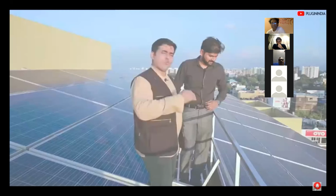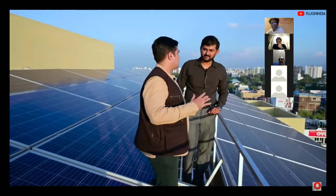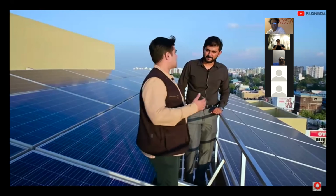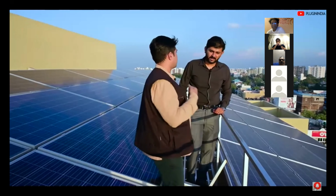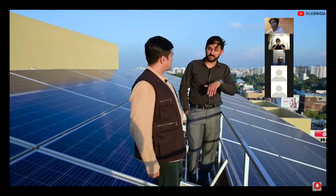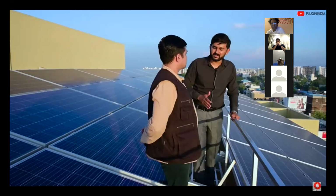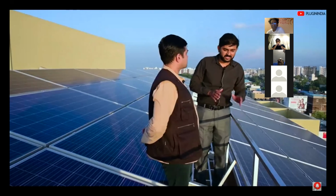Fantastic. 4 months of a year in Pune, you have a pretty cloudy weather. It's the monsoon season. And is there a drop in the production of electricity over here? Yeah, definitely, because the clouds will obviously reduce the amount of sun rays that's coming in. But generation drops to around 60 to 65%. So because of that, yes, there is a drop in power.